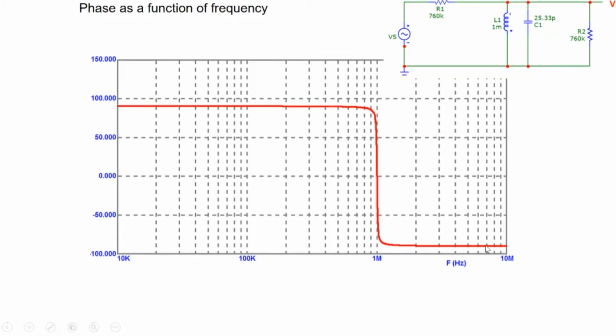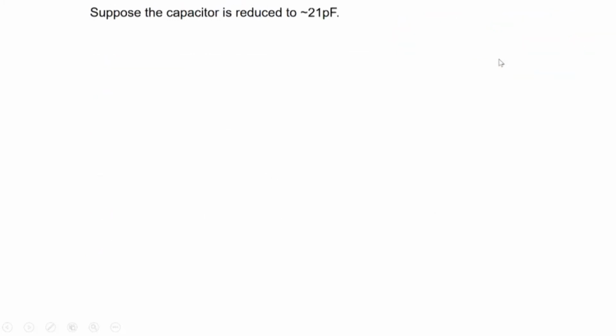While at high frequencies, the inductor impedance omega L becomes high, but the capacitor impedance 1 over omega C becomes low. So the capacitor dominates here and results in negative phase. So the phase response results from the nature of inductance and capacitance, and their behavior at different frequencies.